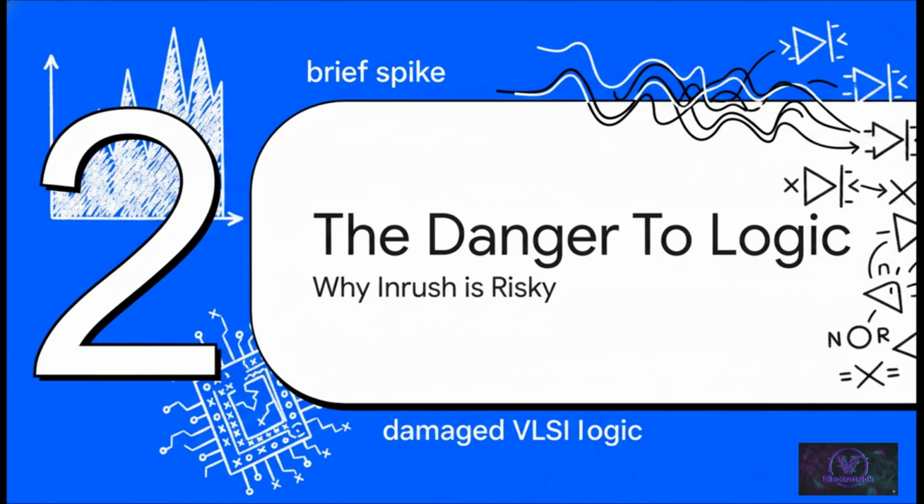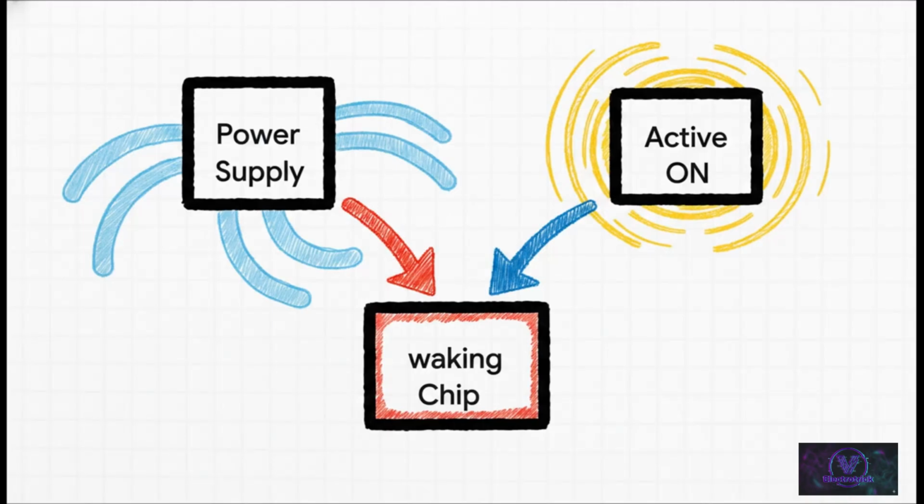Section 2, the danger to logic. Let's look at why this inrush is so risky. Okay, so it's really important to understand exactly where this huge surge of current is coming from. Obviously, your primary power supply, the VDD network, is the main source trying to push that charge. But the second source, that's the sneaky one. It's your neighboring ON logic. This causes something we call the charge sharing effect.